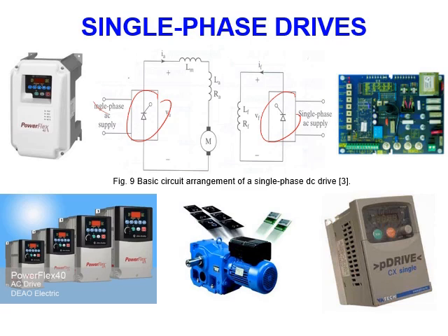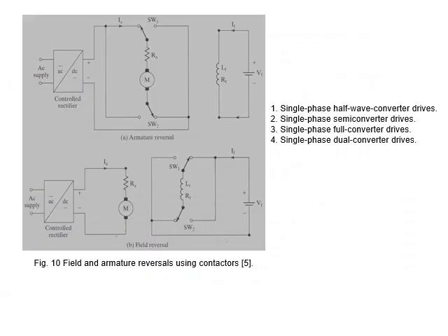Now, how does the circuit look in the box? You get it from the market as a box in different sizes according to your motor. Now you may ask, how do we change the direction of the field current or the armature current? It's very simple. You can see here we put a switch this way. So if we connect here, the current will flow in this direction, back here. If we connect here now, the current will flow in the opposite direction exactly.